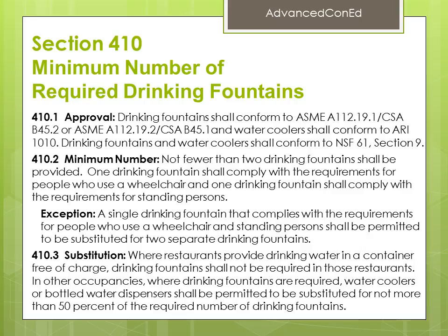410.3 Substitutions. Where restaurants provide drinking water in a container free of charge, drinking fountains shall not be required in those restaurants. In other occupancies, where drinking fountains are required, water coolers or bottled water dispensers shall be permitted to be substituted for not more than 50% of the required number of drinking fountains.